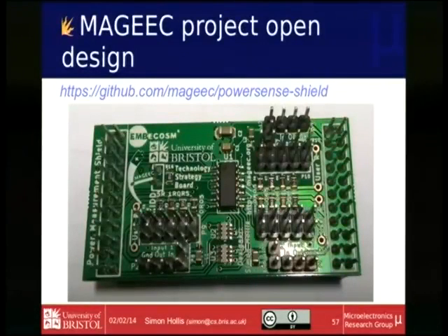This is the amplifier in the middle, the biggest part of the device. We've got a big selection of different resistors that you can insert by connecting to the short. So you have to do some soldering. All you have to do is connect your power supplies into some pins here. So you have to break the power supply trace on the board, take 2 wires out, and push them into here, here, and here, and then that's it.